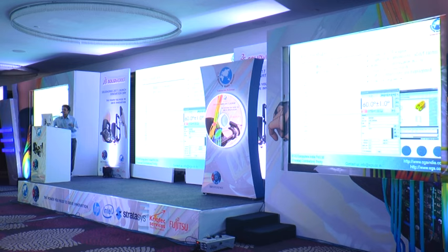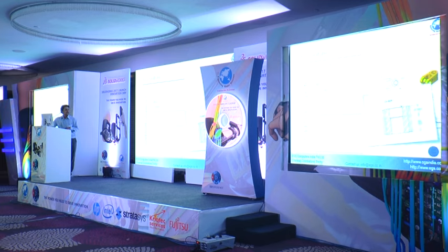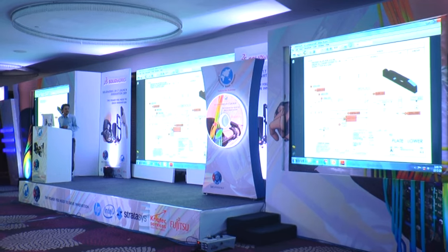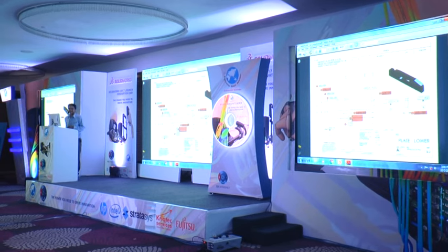sequence. If you delete one of the balloons, automatically the balloons will be sequenced according to the order. Handling a revision drawing: if there is any revision in your drawing, automatically it gets highlighted. I'll show an example. So this is a drawing. If there is any addition compared to the previous revision, it will show in green. If there is any deletion when compared to the previous revision, it will show in red. In that manner, you can easily compare all the previous revisions with your current revision, and you can start ballooning. No need to start from scratch.